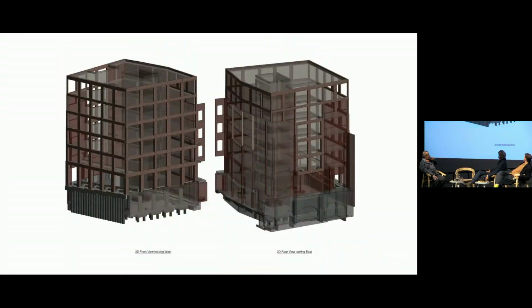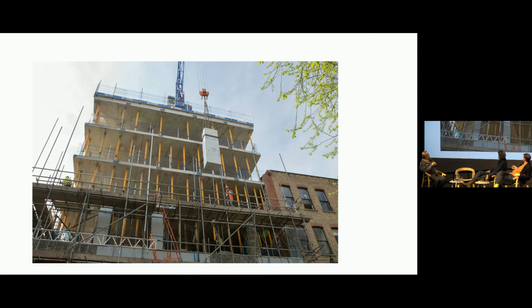Moving on with the idea of using stone. Actually, this is Clark and Well Close, which is exhibited downstairs, and it's Amin's own project. This is our Revit model: concrete slabs and a concrete core, and then a stone facade. And the stone facade is entirely load-bearing, so there are no other columns in the building. All the weight of the slabs goes down the stone facade.